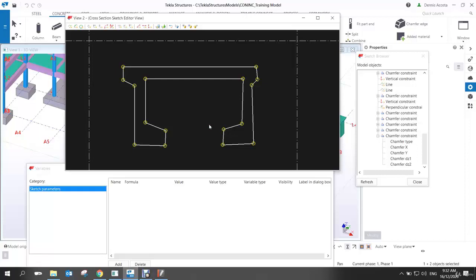You cannot just simply create a square and then expect that it will form the shape. Sir, in Sketch Editor, how do you turn off the snap for the orthogonal? Press O. Just O.